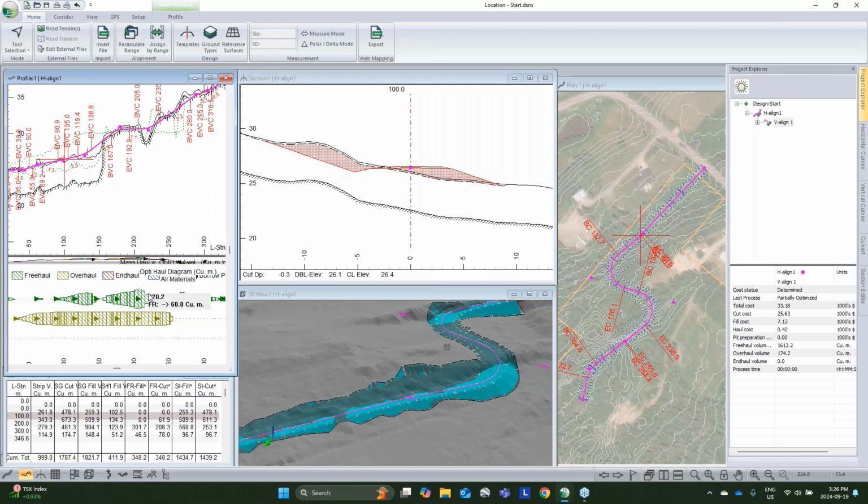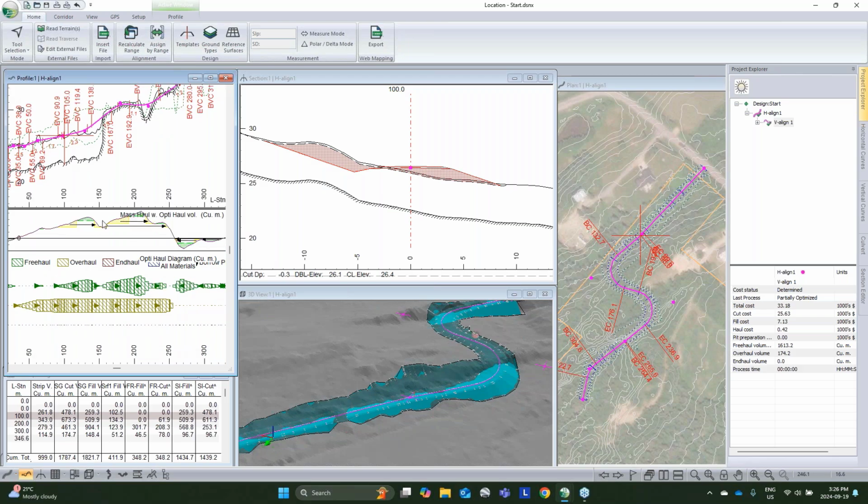But in the slide Aaron had, if we have spots where we need a certain material for a certain type of fill, then we don't get cases that are simple, which are still reasonably well estimated with just the simple mass haul diagram. We end up with different material coming from one location going to another to account for those construction realities. And with that, I'll leave it there. I'll let Darren introduce our next topic.